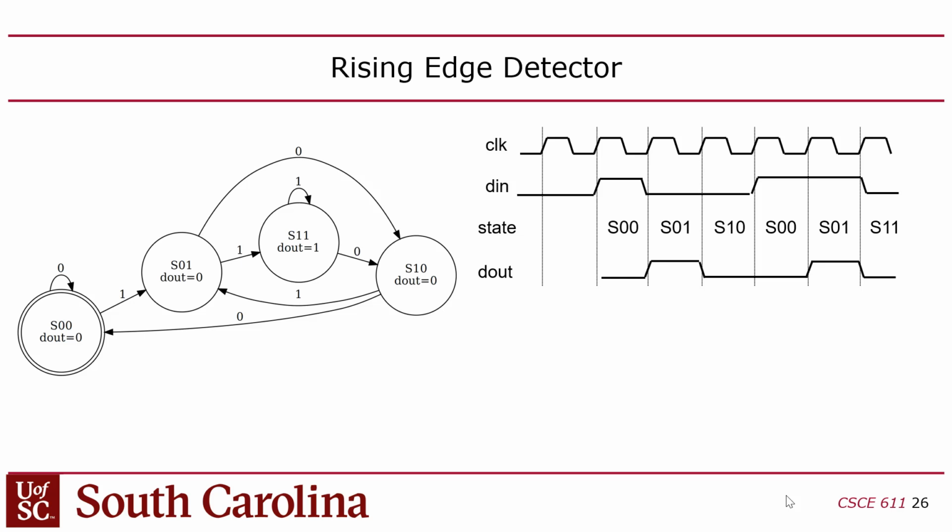So there's a couple different ways you can do this. My solution in class was to just create a shift register that would keep track of the last 2 values of the input, right? And then you could use combinational logic just to set it to 1 whenever the current or the most recent input is 1 and the one before that was 0, right? That would be a rising edge. You can also design that with a state machine, which is the way they did it on the solution on ChipDev. And this is where things start to get a little complicated, though, in terms of picking states.